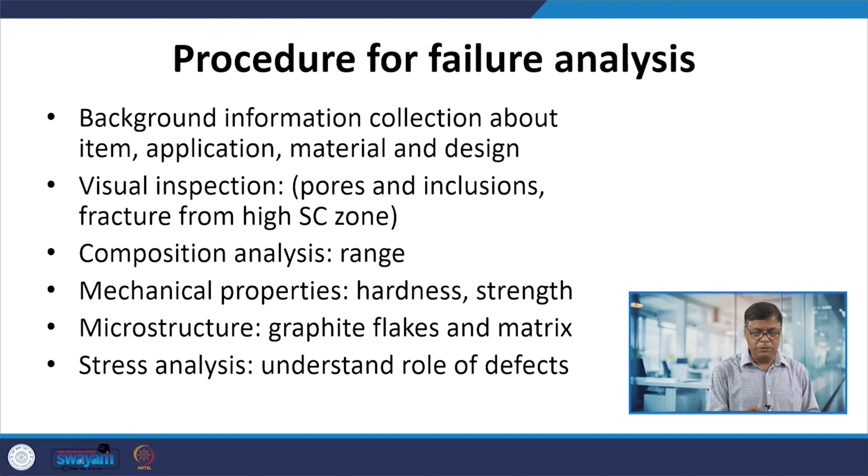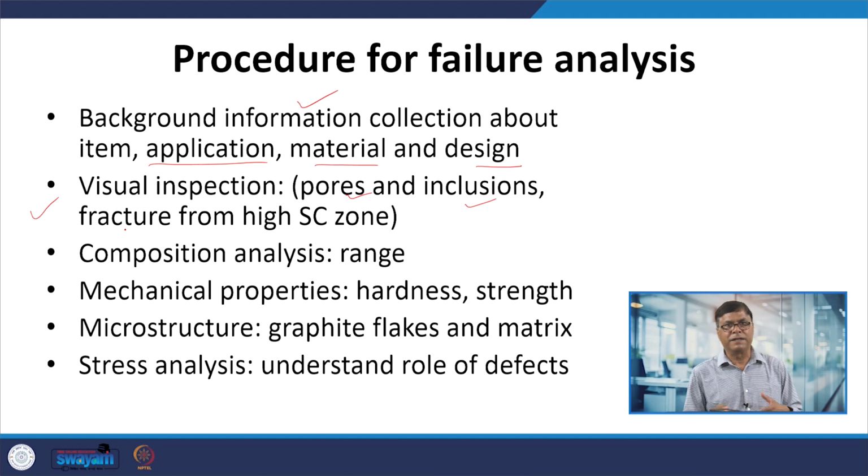So, do the background information collection, and since we have already talked about this, it is cast iron of a given design, and the application is regulating the flow of water. Okay. So, the next step after familiarizing is to inspect. Inspection showed that the fracture surface has porosity and inclusions, and the fracture basically triggered from the high stress concentration zone. Okay.